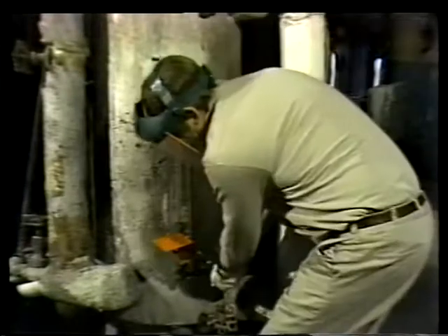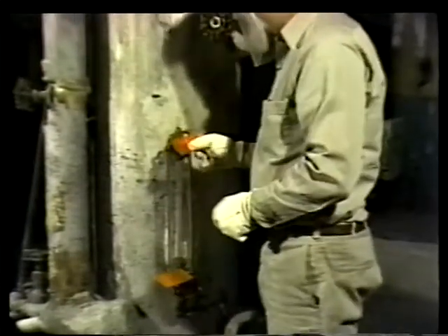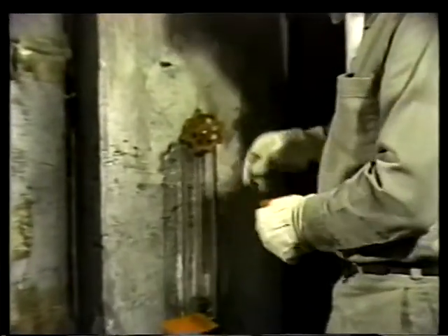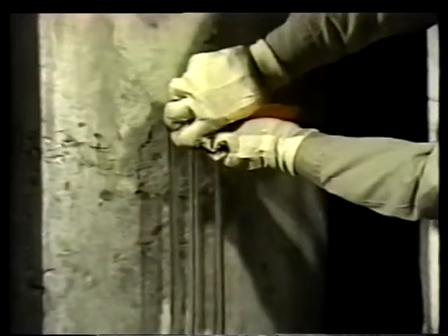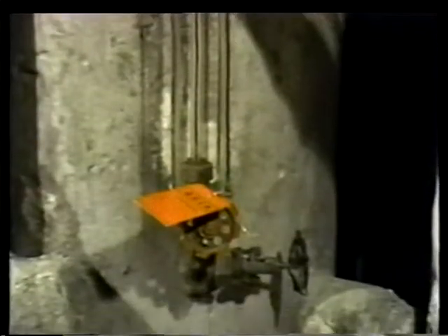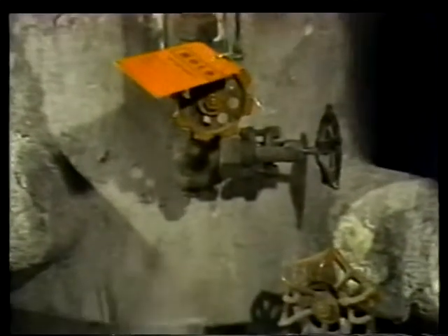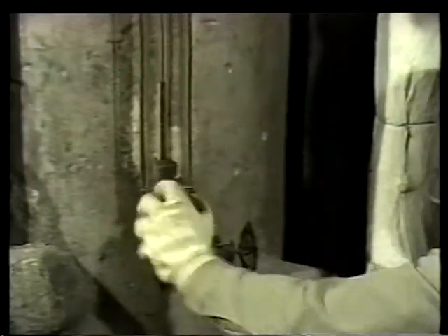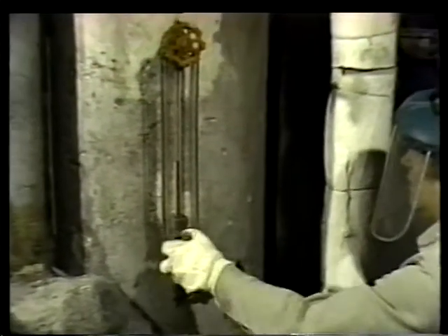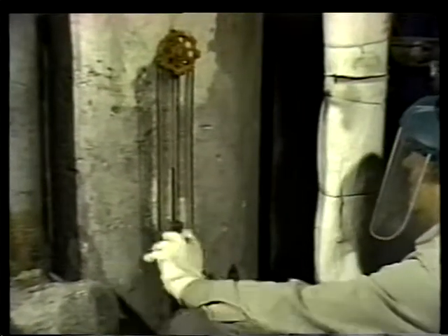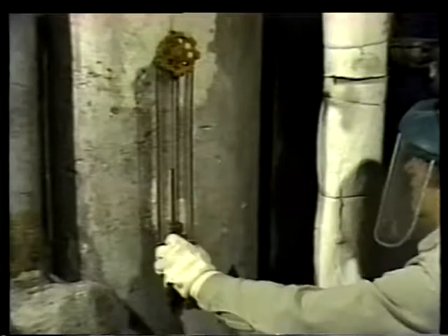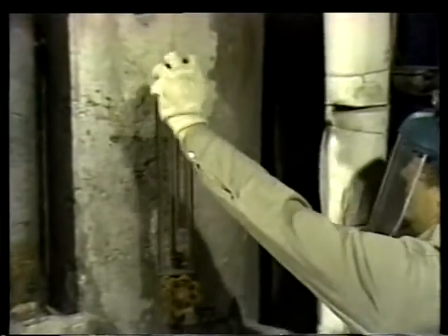If the fluid in the tank or vessel is hot, the gauge should be warmed up slowly. Now, this is done by cracking open the upper gauge valve with the gauge drain wide open. When the gauge is warm, the drain is closed. And both isolation valves are opened wide. This puts the gauge in service. Then it should be checked for leaks. Once this is done, the procedure is complete.